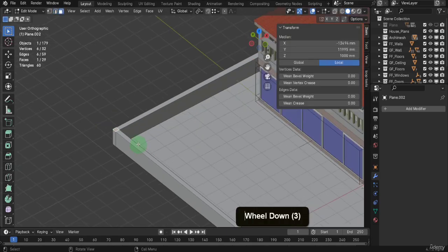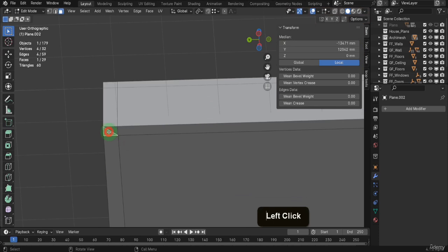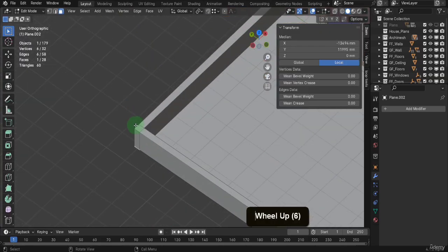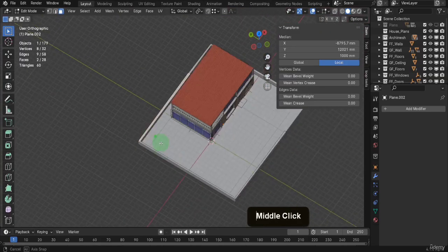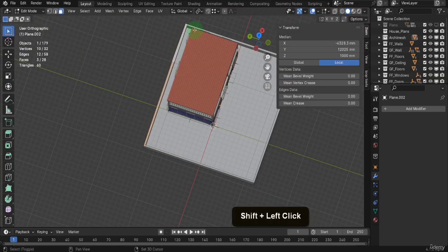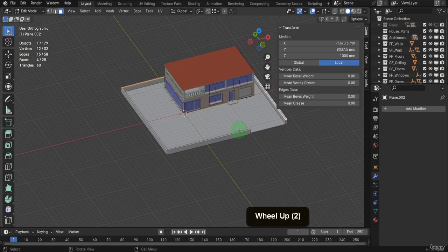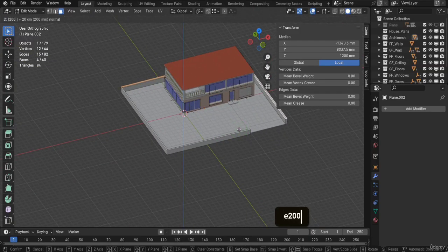Now select the two top triangles. Press F to form one face. Repeat this underneath and select these two faces. Press F and form a face. Next, we can select the faces we need to extrude, so the back and right side wall, including the two small squares we formed. Press E, input 2000 and enter.